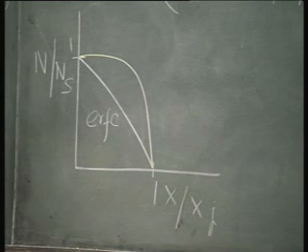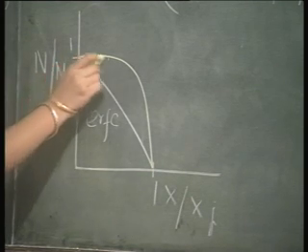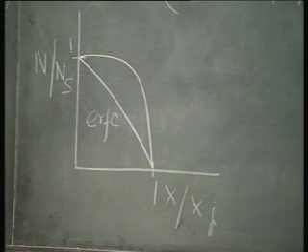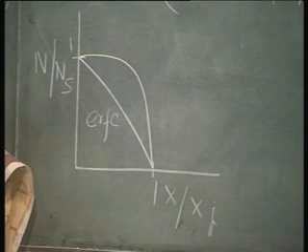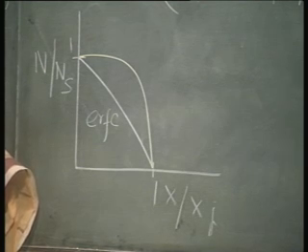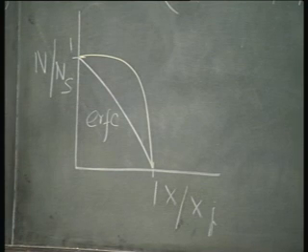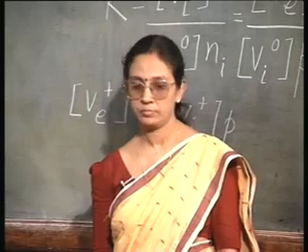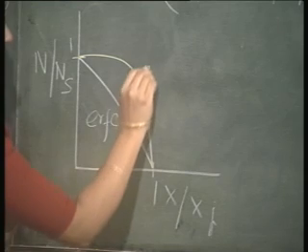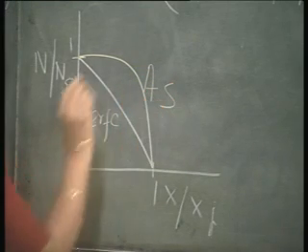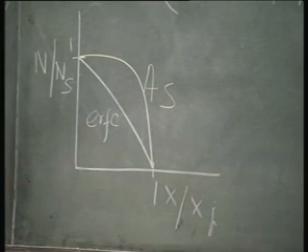What do I mean by more abrupt? That is, the concentration will be closer to the surface concentration over a larger depth, and then it will fall steeply at the junction. So, this is what the profile is going to look like, arsenic profile in silicon, right.